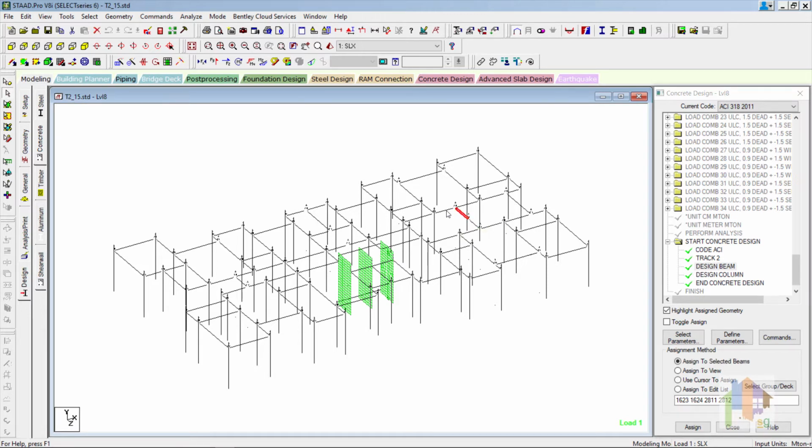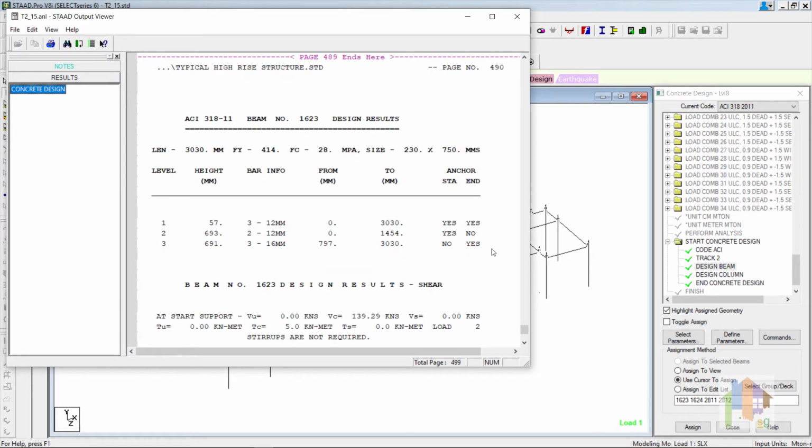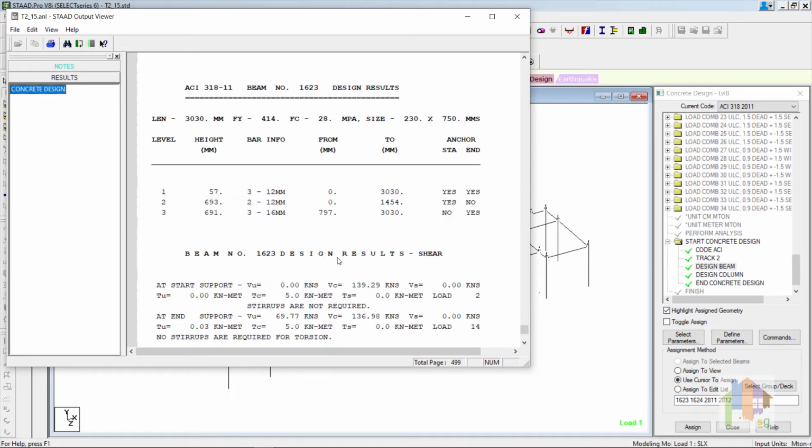When design is performed, the program considers the analysis results and provides a reinforcement value for each individual member. The problem is, in reality, these beam segments are not separate; rather, they are part of a continuous member. So, when different reinforcement values are provided to adjacent members, it is not feasible on site. You need to manually adjust the reinforcement to provide uniform reinforcement throughout the member length.